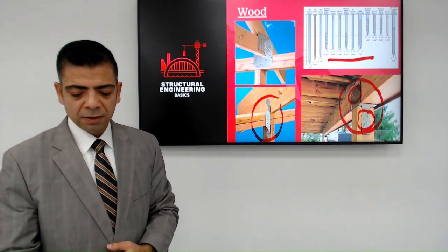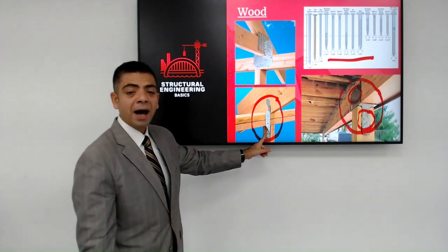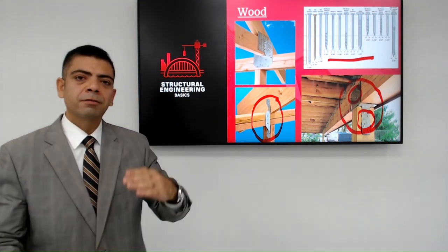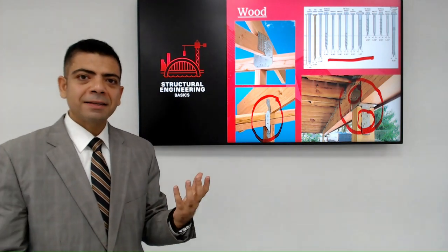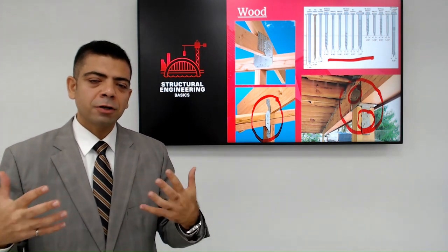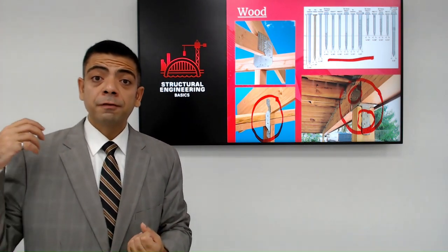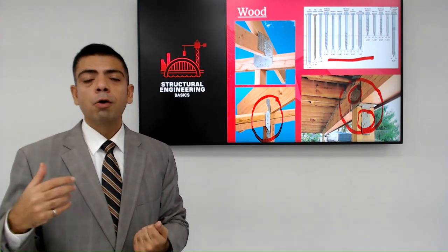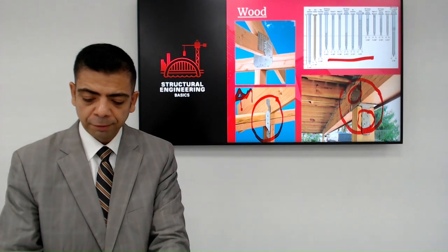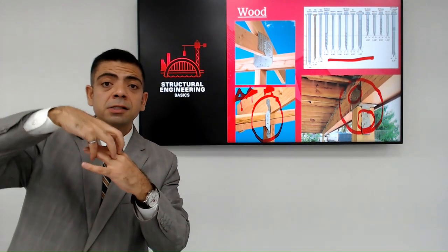This is a very interesting feature. I always had to go and check for a tie or an element like this. The main function is to hold the roof to the rest of the structure. This is, I guess, a disadvantage of wood being on the light side. The structures made of wood are usually lighter than other construction materials. So in a case of very high wind speeds, like a hurricane or a storm, there is usually suction, upward uplift due to wind.